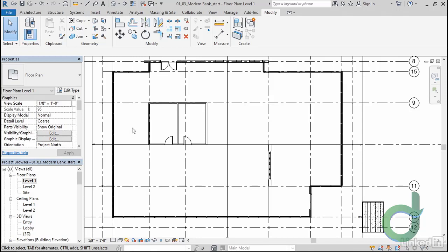The other reason to break up objects like the ceiling is to make sure that you've got the ability to show enough lights on each piece, especially if you're dealing in real-time lighting. If we're dealing with one big ceiling here with a hole punched in it, there's a good chance that we'll start to see lights wink out in a real-time simulation. What that means is that an object can only have a certain number of lights on it. And so the more objects we have, the more each one can support multiple lights and so look right in our lighting.